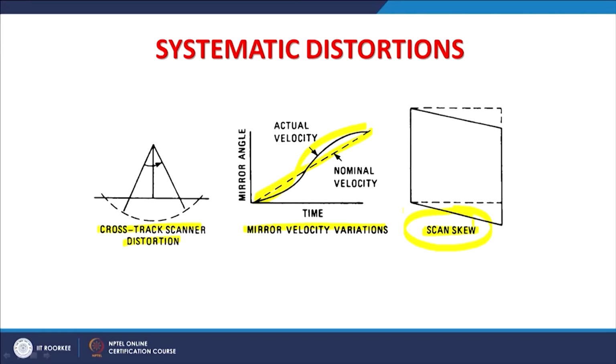Anyway, the orbit is also not exactly from north to south, but it has roughly a 9-degree angle in many cases, and it is moving around the Earth like this. So, if it is moving and in between the Earth rotates, this will bring this error in a large form, which is called scan skewness. This error too can be removed by employing georeferencing.